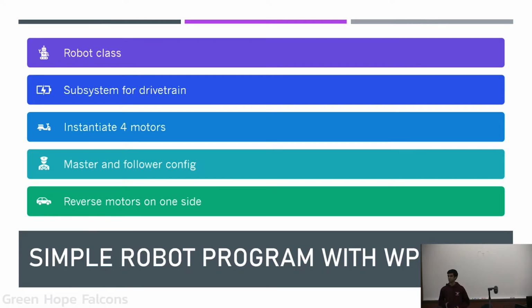So why do you think path following is important in the autonomous period? Why don't you just drive forward, stop, turn 90 degrees, and then move forward again? Why is it so important? Well, it could be like, it's really smooth instead of individual steps. Like it's the ability to do things really quickly and much faster. Yeah, so trajectory tracking is usually a lot quicker because you don't have to really stop along the way, and oftentimes it's actually more accurate.